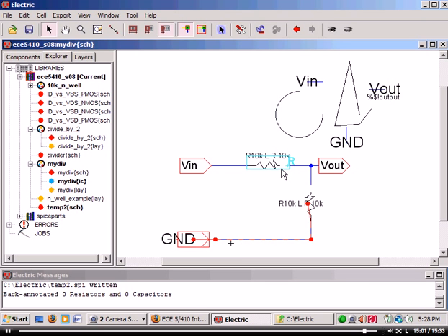So if you want it to be for all of your SPICE simulation stuff, you have to put it in the top ranking cell. So generally what I'll do, you'll find later, is I'll do a design, and then for the simulation, I'll just put the design in a cell that's called design underscore sim, or underscore sim1, and then go from there.